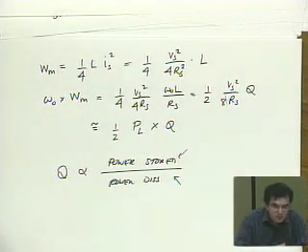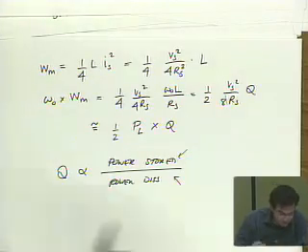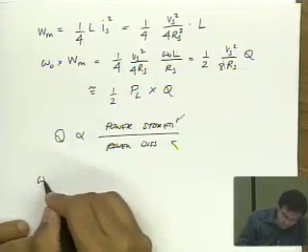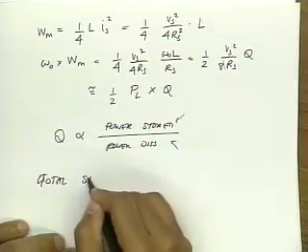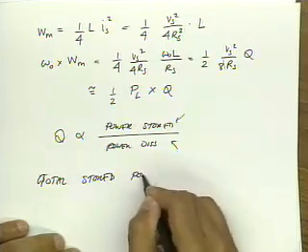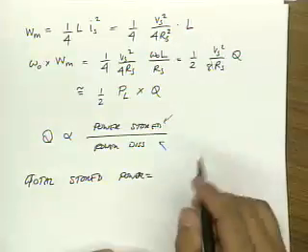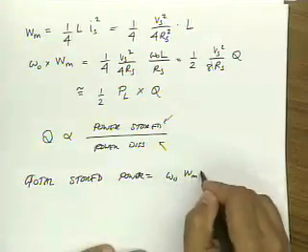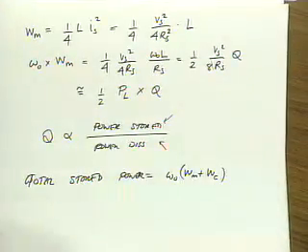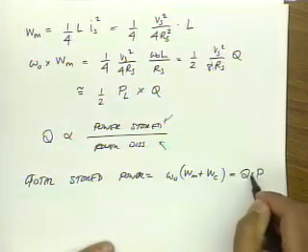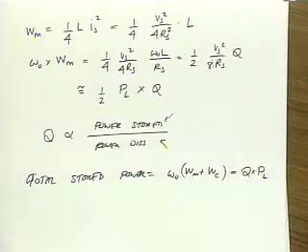It turns out for second order circuits, these different definitions are actually equivalent. But let me not get distracted too much. So the important point is that if I look at the total stored power, at resonance, the power stored in the inductor is equal to the power stored in the capacitor. And so this factor of 1/2 goes away, and I just have Q times the power that's going into the load. Okay? So now this is the important part.